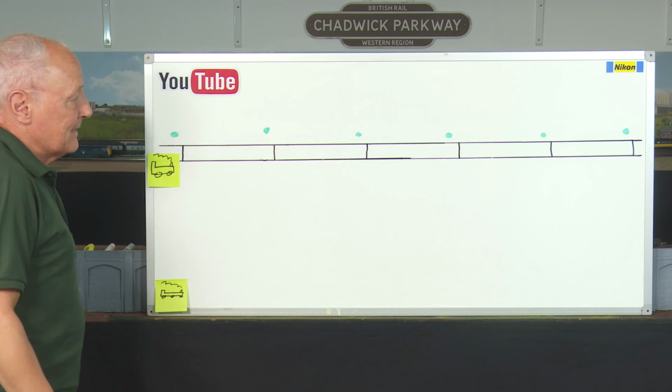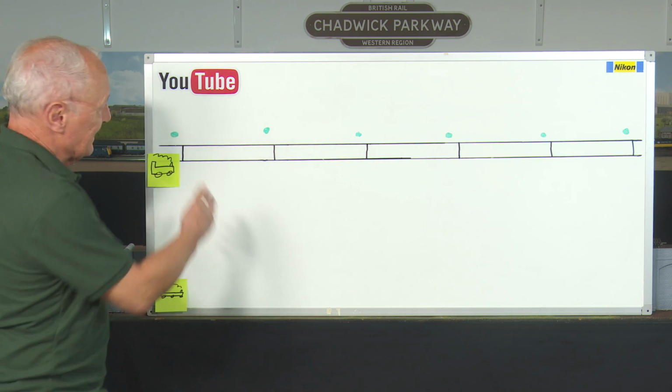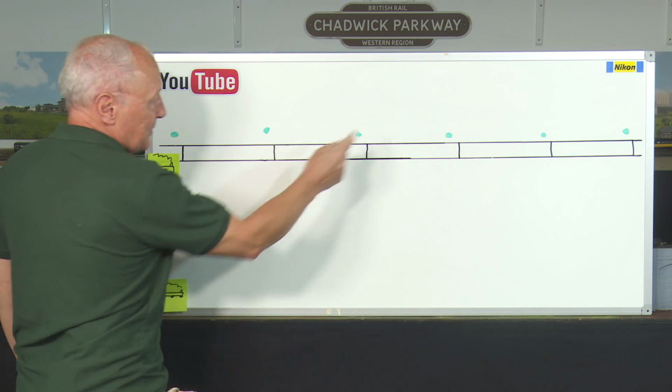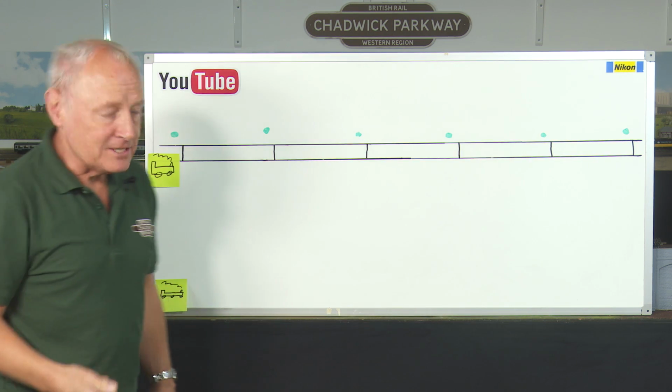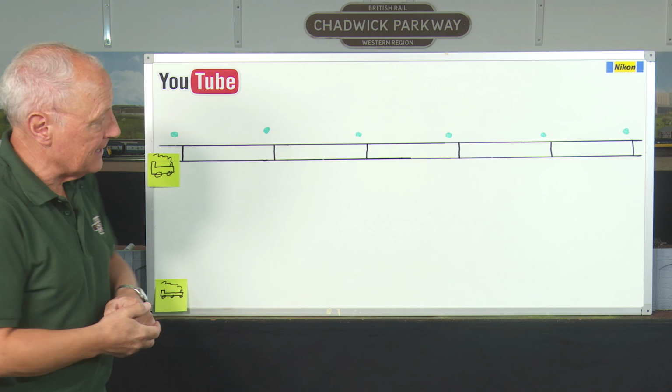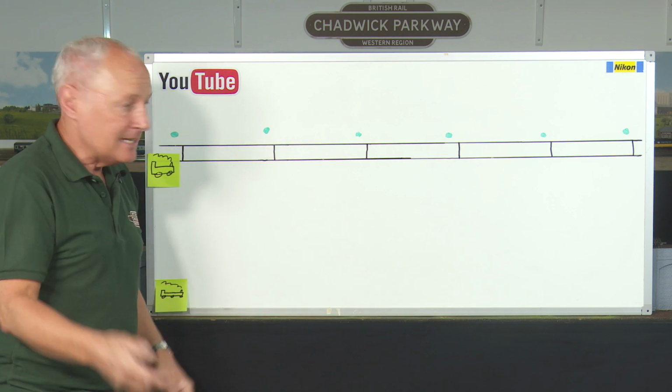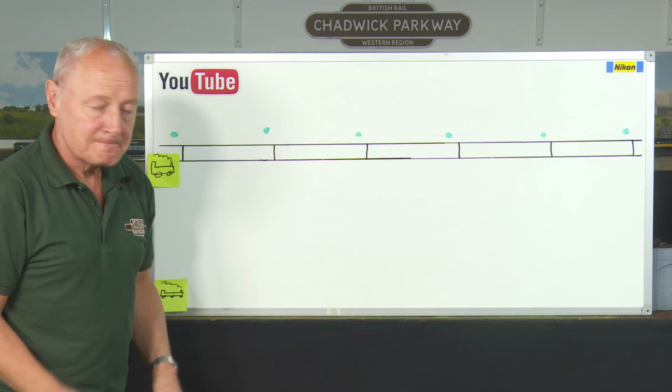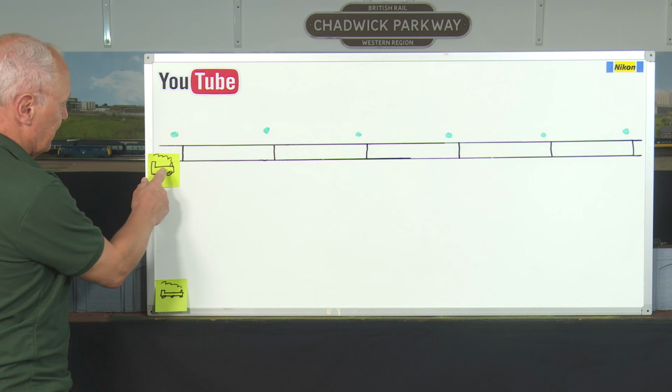Railways are generally split into blocks, and a train will enter a block from another block and go to another block, quite obviously. But the blocks are there to provide safety between trains over time and distance. So let's take a look how that works. For illustration purposes, here's our train line and here are the blocks. As a default setting, all the blocks these days are set to green, as in clear, so trains can run straight through them. So along comes our first train.